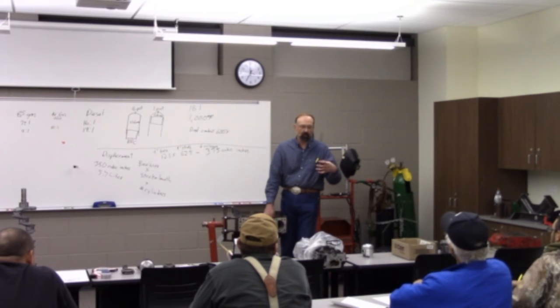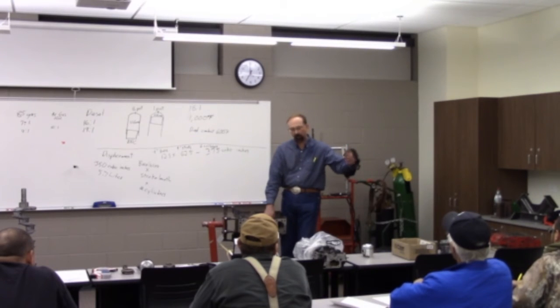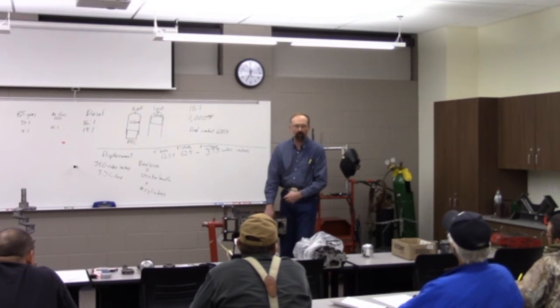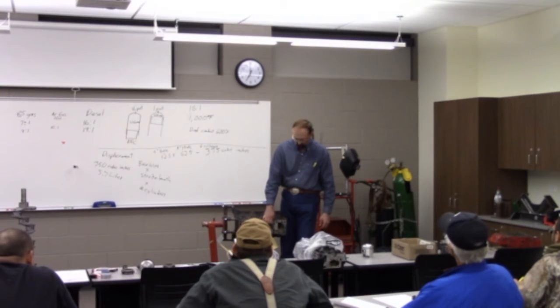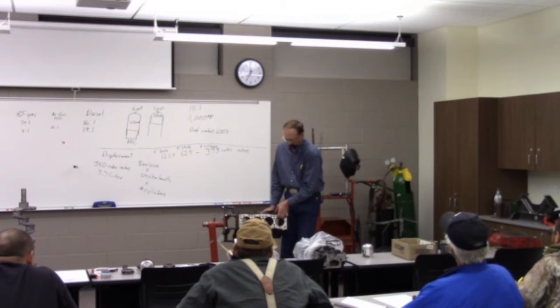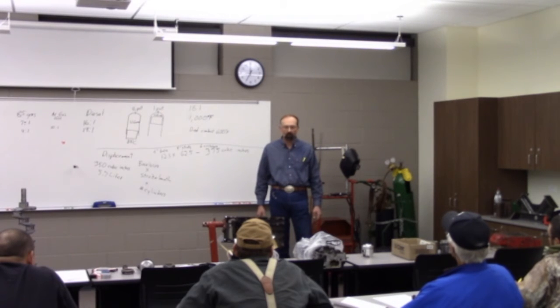And what they do at 2 millimeters is they'll bore that cylinder 2 millimeters over, then there's a repair sleeve that presses in it, and then it gets bored back to the original size, and you put an original size piston back in it. But that repair sleeve is not normally used unless the wear or the damage is pretty extreme.